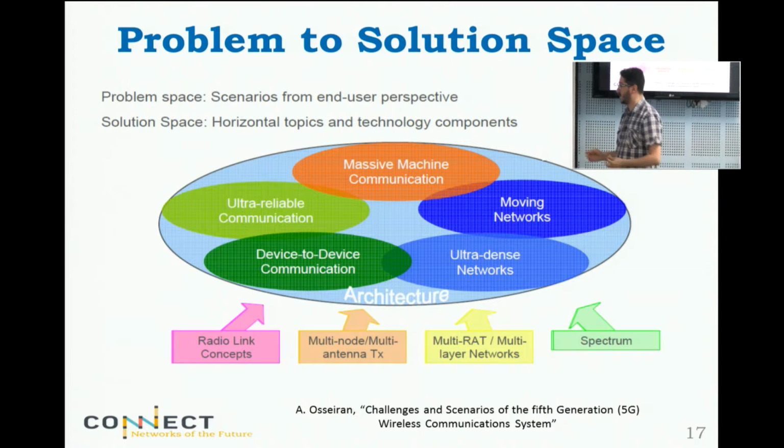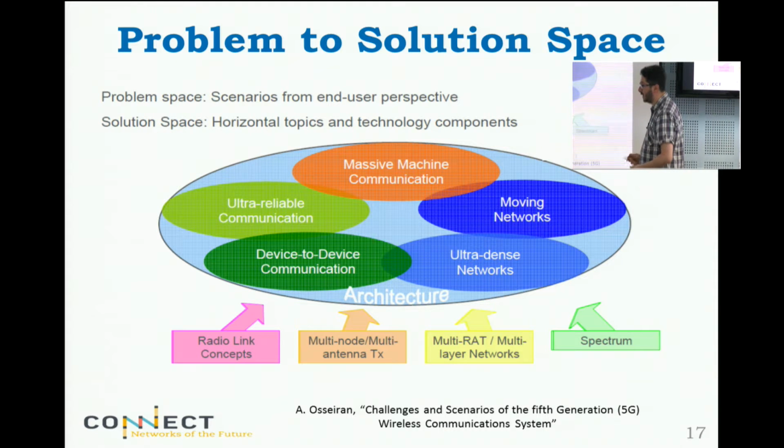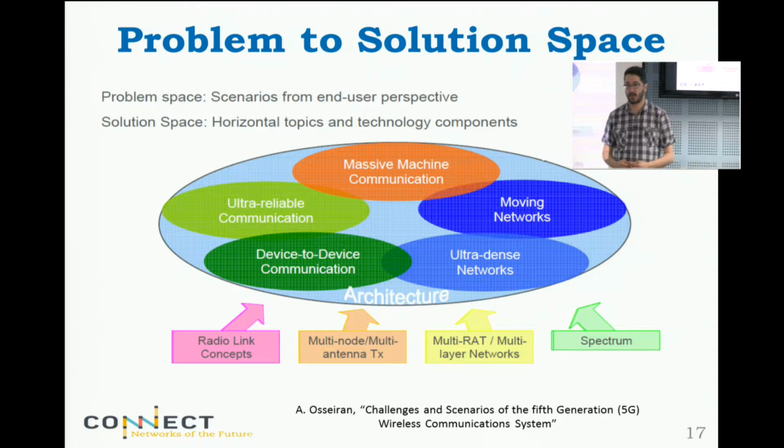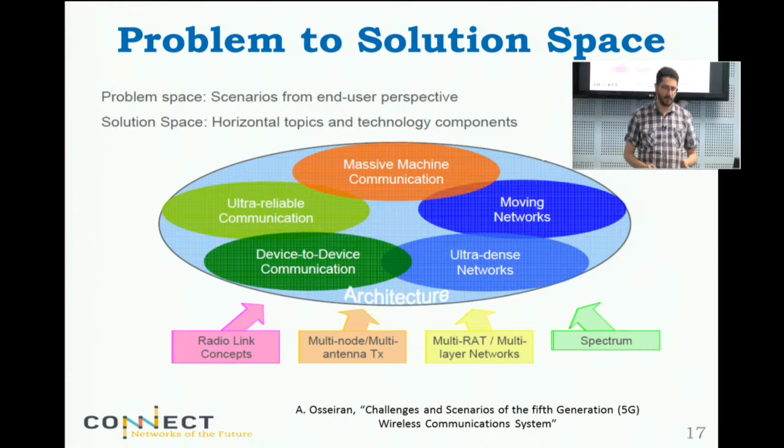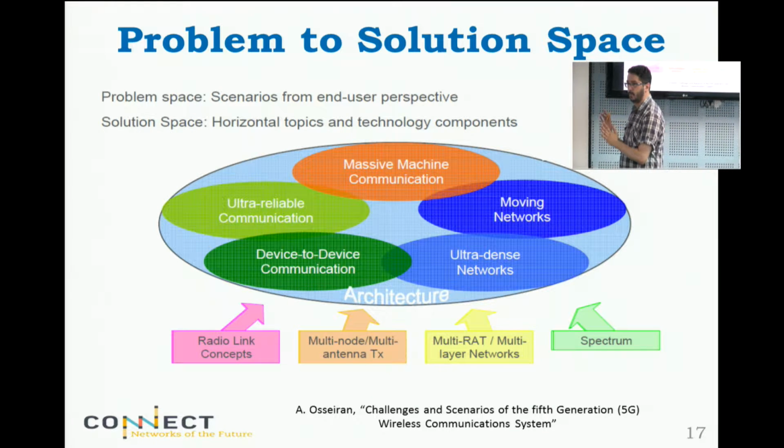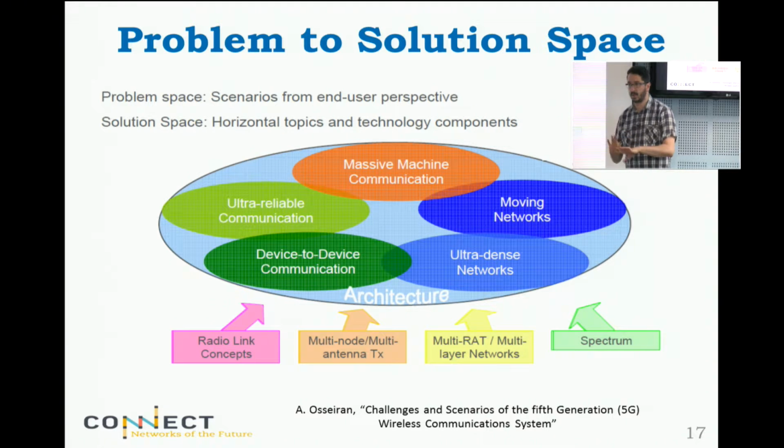Radio link concepts, I mean basically other PHY techniques. So you do have advanced coding schemes being investigated, like short frame codes. LDPC has been there for a while, so I don't consider it really so new. And then definitely new waveforms. We're going deeper into that later in the course, but the idea is that you basically move away from one waveform for all the network, okay? And you start to have a set of options, depending on what you have to do.